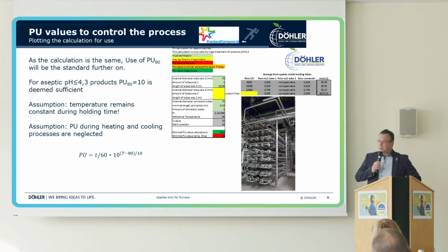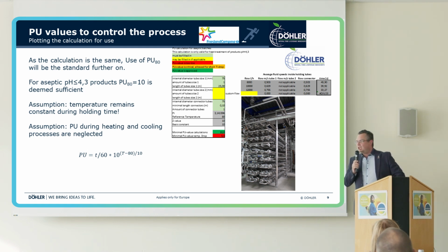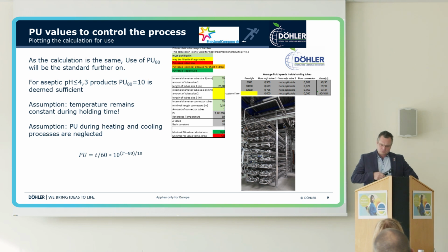What you see here, if I would put my lower limit of the heat treatment at 10 pasteurization units, then usually if I would go for the maximum capacity of 12 cubic meters per hour, it will be put on 93 degrees Celsius that your heat treatment will be performed. The lower limit that the line should go out of production back into circulation, I would put that at, say, 90 degrees Celsius, or basically 5 pasteurization units. And if I would slow down my production line, I could actually go down, for example, to 91 degrees Celsius.